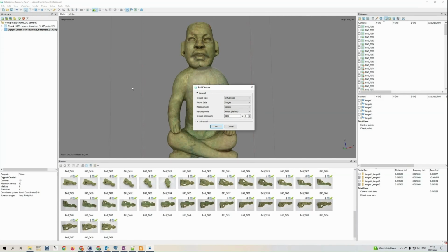Under this command, we can select different texture types, the source of the color values, the type of conversion, and the complexity of the texture. For the most part, we leave it at the default settings, but set the texture to a lower resolution at the count of 1, which is sufficient for us. Subsequently, we derive a photorealistic surface from the images that completely encompasses the model.